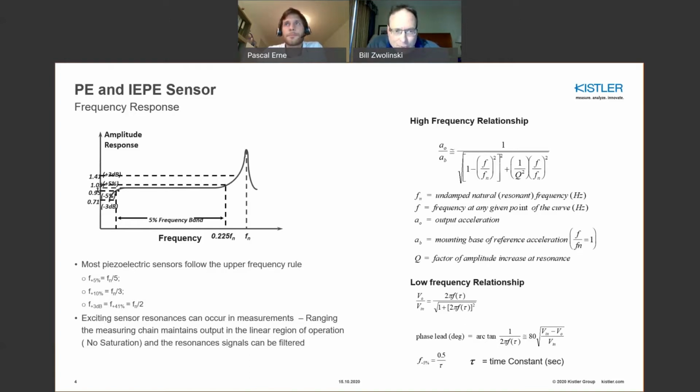So why is that important? Well, because when we're making force measurement platforms, we're always interested in what the test article needs. Once you know what the test article needs, you can look at the response of the design, how it works, the FEA, and apply some of these rules as a guide. Obviously the detailed analysis is very much required in that, but these are guidelines. So this is something we'll probably come back to a few times during the discussion anyway.